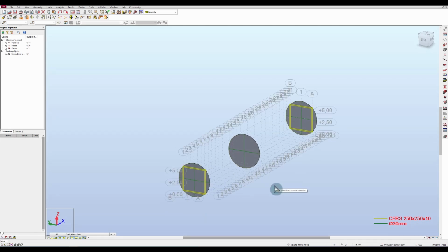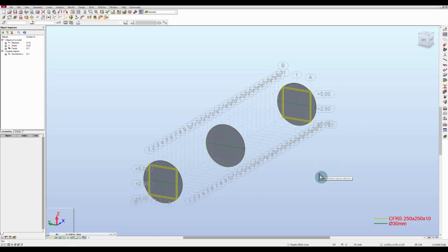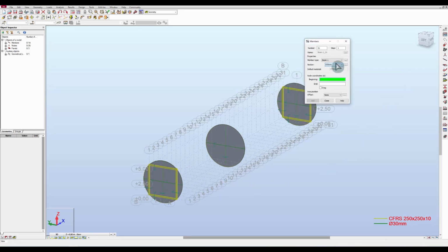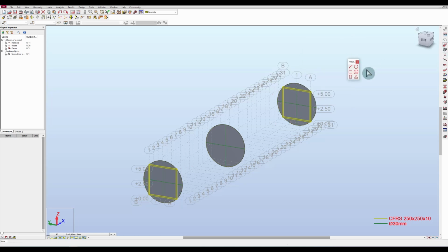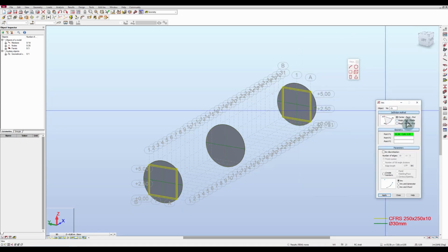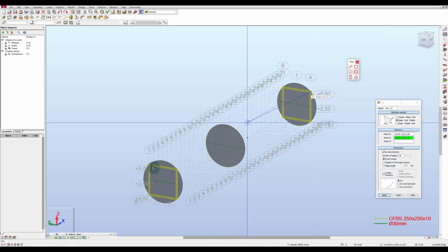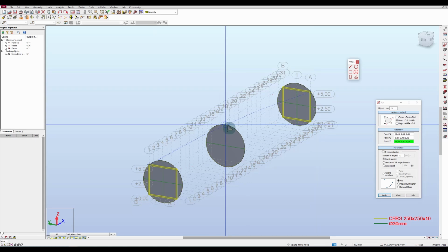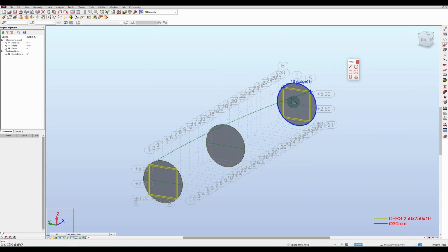Let us now proceed to the next stage in the modeling of the twisting bridge. In this phase, we will focus on creating the curved beams, which are positioned at the top, bottom, left, and right sides of the structure, effectively forming a complete perimeter in 4 directions. To achieve this, we will utilize a curved object, which will then be subdivided into 13 equal segments.